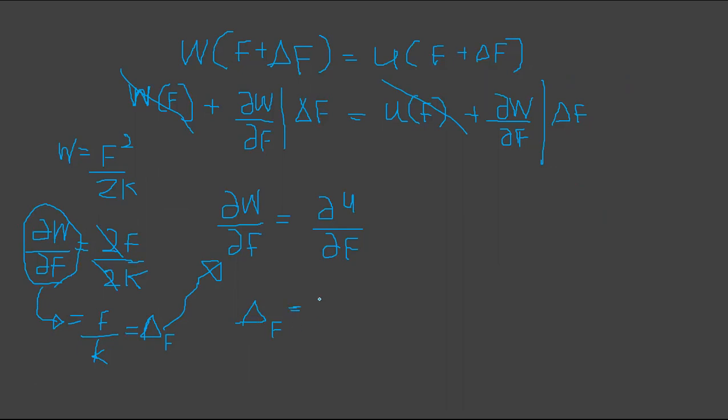So that's how you link two theorems together. Castigliano is saying if you differentiate partially the strain energy with respect to the force in that direction, you are getting the displacement. That's the simplest meaning. This is Castigliano's theorem.